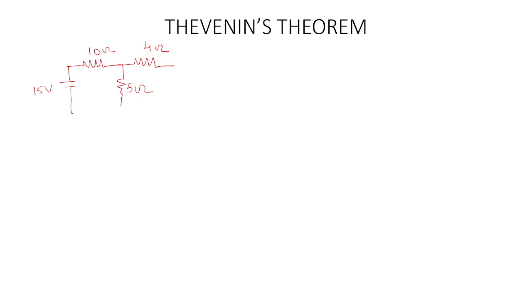Voltage is 15 volts and here the voltage is 9 volts. So we have to calculate the current flowing through 5 ohms using Thevenin's theorem. So this has to be converted into V Thevenin in series with R Thevenin, and then the voltage across the terminals should be the load resistance here, RL, which is 5 ohms, because we have to calculate the response in 5 ohms, right.